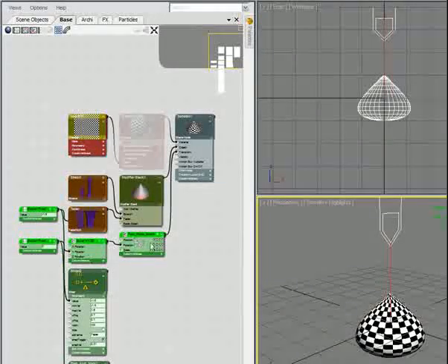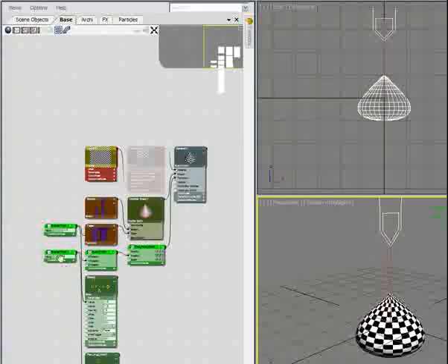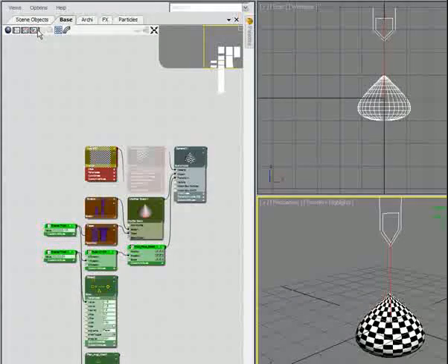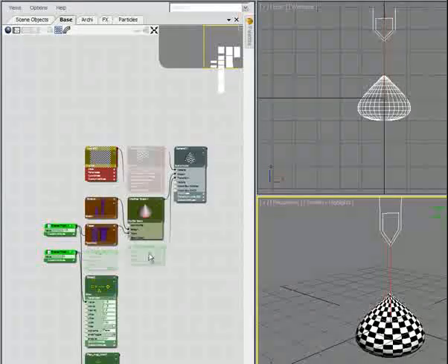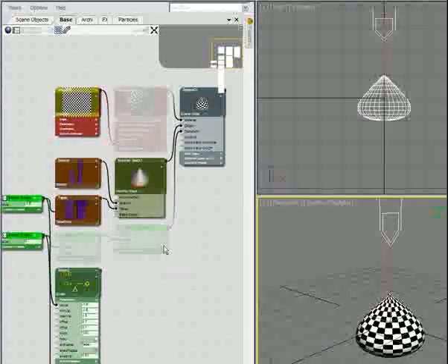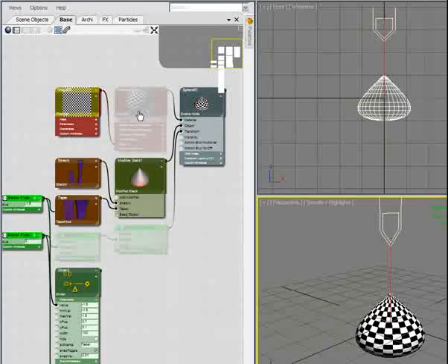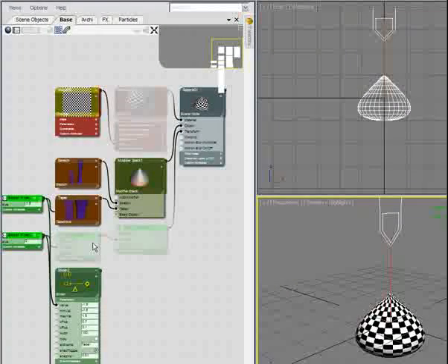The other things I might not want to see are these two controllers which lead up to the final one, and I could hide a couple of controllers, and you can see them get subdued there by opacity. So this is a great feature of Zookeeper where you can filter and bring down the opacity of any nodes that you have in the scene.